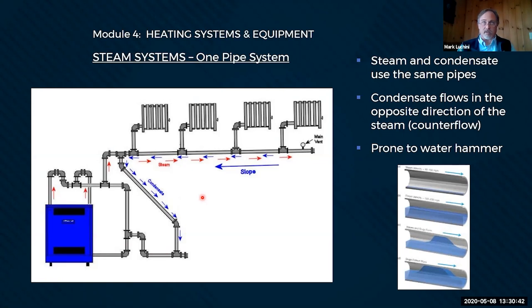And these things will move at the speed of sound. So imagine a 30-pound slug of water heading towards the end of a 6 or 8 inch pipe. It blew the elbow off the pipe inside the manhole that he was working on and basically cooked him. So it's something to be very concerned about, very careful with.